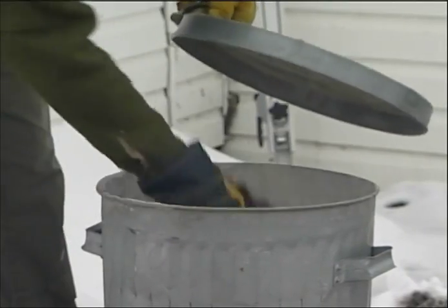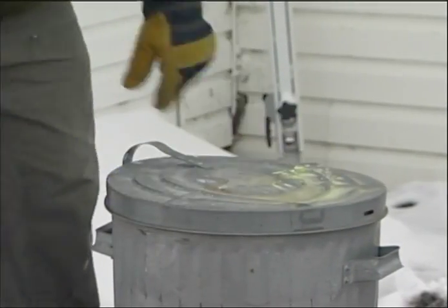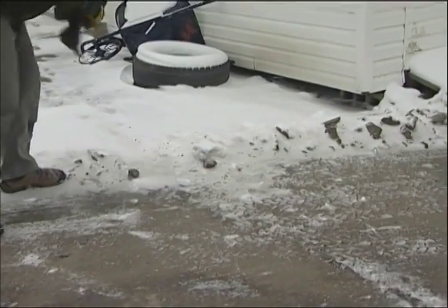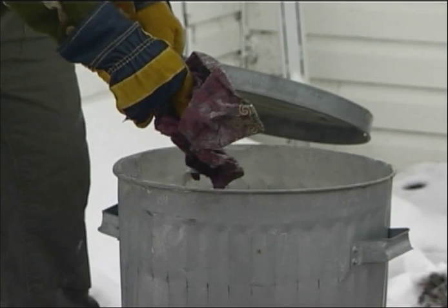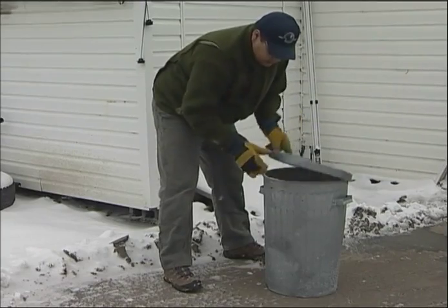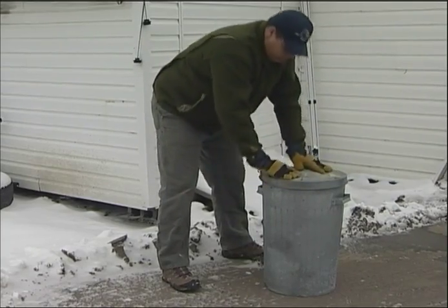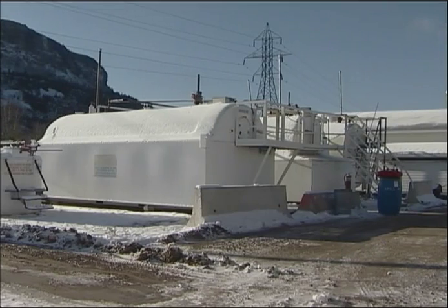A steel garbage can with a lid for oily rags and garbage is required. Oily rags can spontaneously combust and all precautions must be taken to ensure that used Kim towels and rags are placed in a fireproof can and stored away from fuel operations.